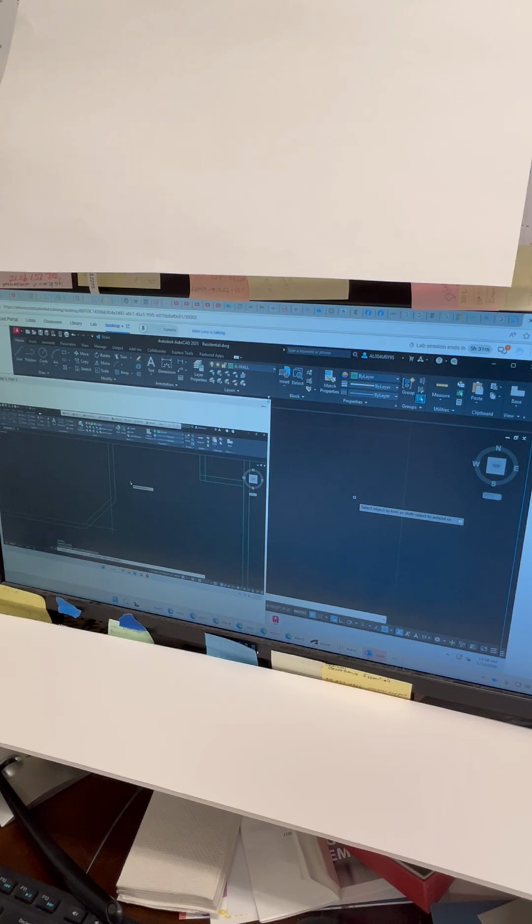Now, as I said, I've already checked it, and I'm pretty sure everybody's radius is 0. But just to make sure, check to see that your radius option is set to 0. So in this case now, I hit the down arrow on my keyboard. There's radius, and it's 0. That's perfect. I'm going to accept that. Now, before I do anything, I've got several places I want to fillet. So this is a perfect example of I want to use a multiple fillet. The multiple option, I should say.